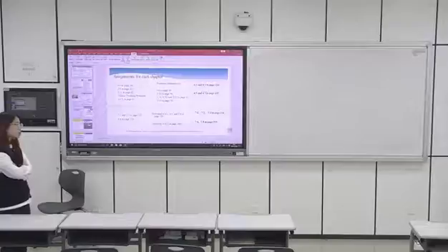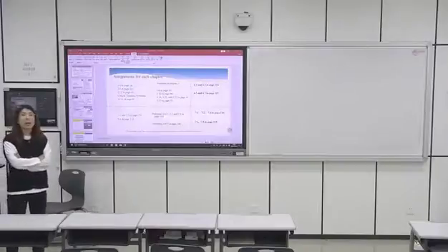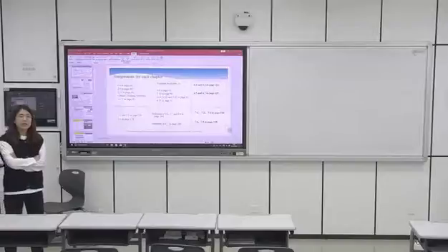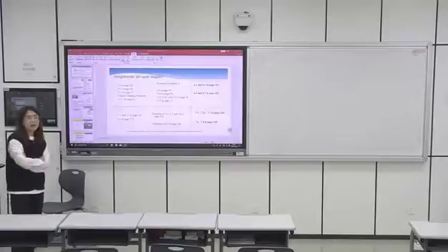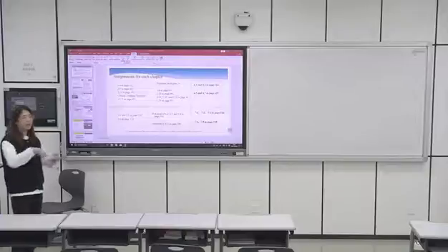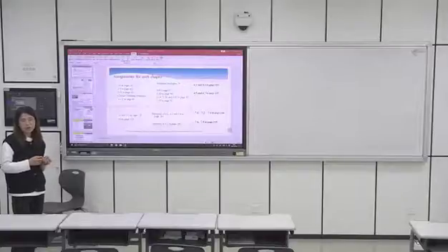Origin of soil, how soil comes from. But in the second chapter, the main thing is about what? It's about the particle size distribution, right? The mechanical analysis. So we learned the particle size distribution curve, how we get the particle size distribution curve, and how we calculate CC and CU of a soil. And what is CU and CC? CU is the uniformity coefficient, CC is the coefficient of curvature, right?